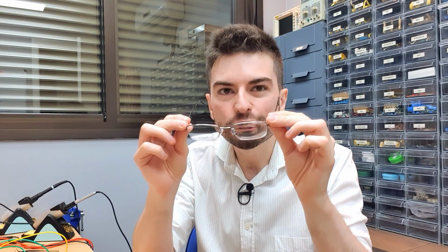Because as noise spreads over frequency, a white noise source has energy over every frequency we analyze. The amount of noise power we get is proportional to the bandwidth that we are using to look at the noise. If we increase the bandwidth of the measurement, we are going to measure more absolute noise power, as we are collecting more frequency bins, you see, that are available from this noise source. We are looking at the noise using a broader lens.